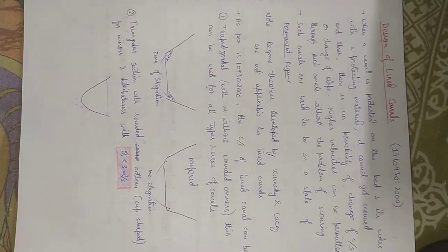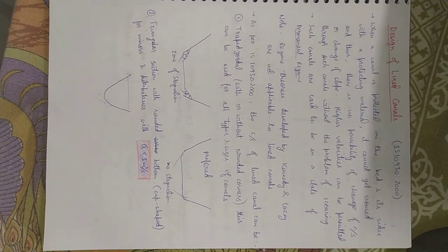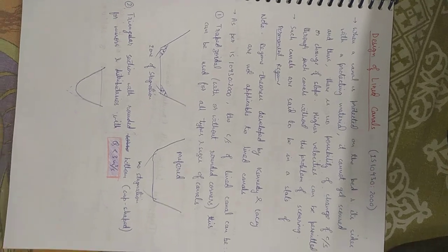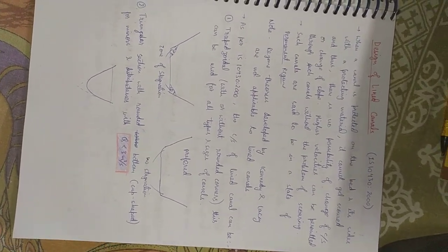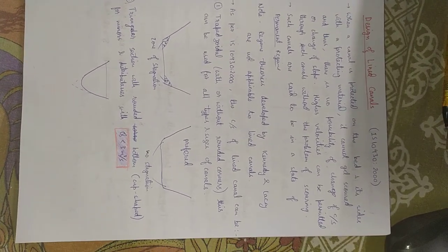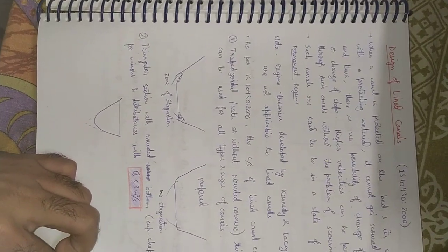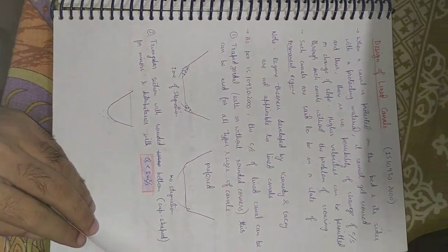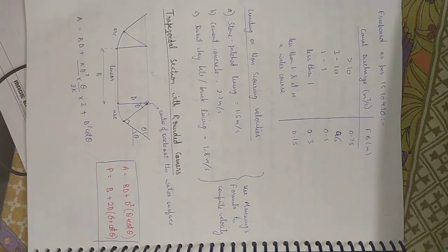So, this is revision day 2, design of lined canals. Yesterday we read all about design of unlined canals, and so in lined canals, while designing, we consider the shape of cross section to have rounded corners, not sharp corners, and the shape can be trapezoidal or triangular with rounded corners, of course. And regarding freeboard, there are certain